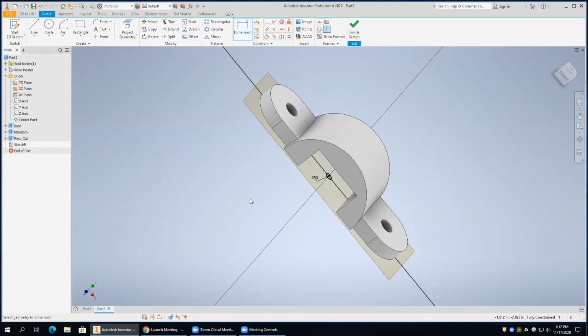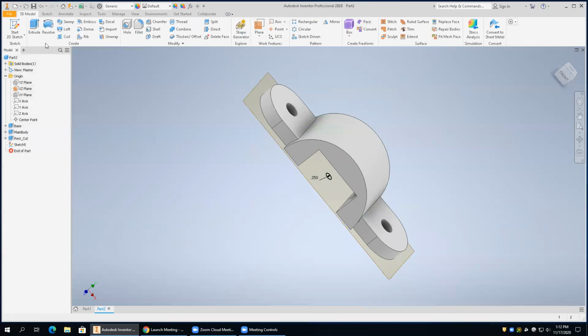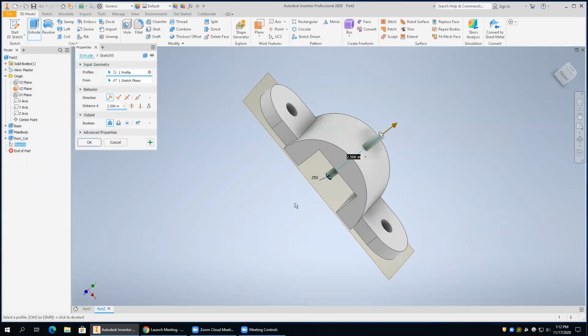Okay. So instead of having it attached to that upper surface, we now have it attached down to something different. We're going to extrude that up, and now whether that cut feature is there or not, the drill hole should still work. Once you have this placed and dimensioned, go ahead and finish the sketch. We're going to extrude that. Make sure you're doing a cut extrusion.